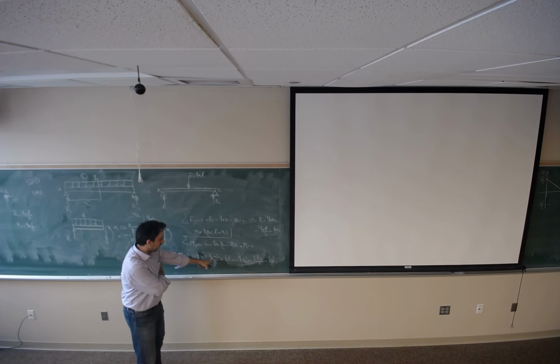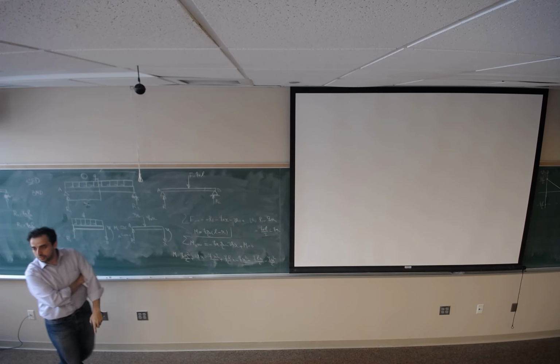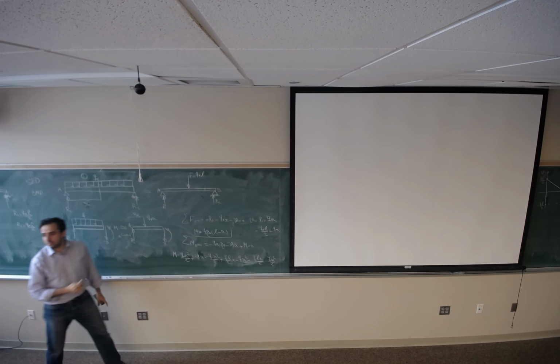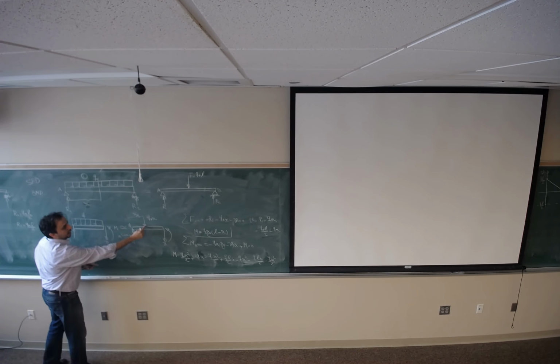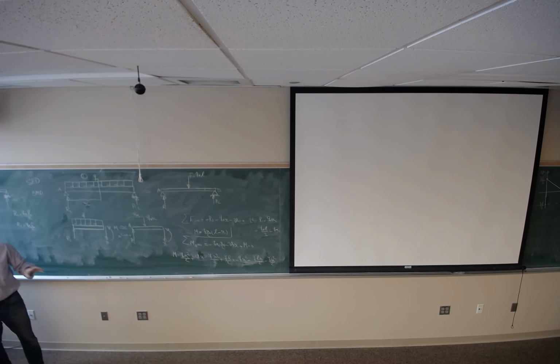I have a question. Yes. In the sum of the moment at A equals 0, it says equals negative. Is that QX times X over 2? Yes, negative QX times X divided by 2. This is the distance, and this is the magnitude of the force. QX times the distance, how much moment is it making? Does it make sense? Okay.